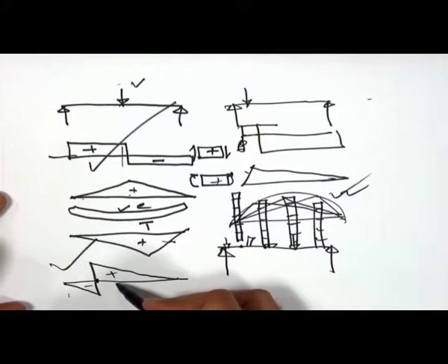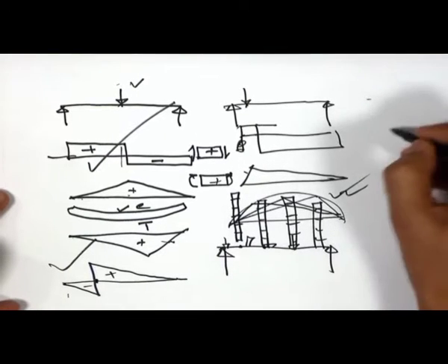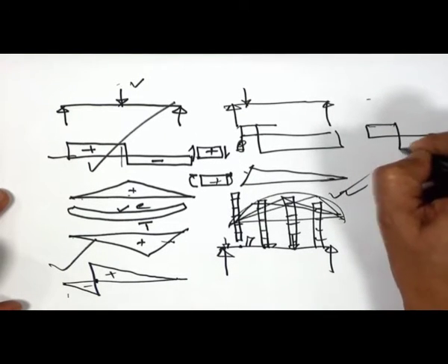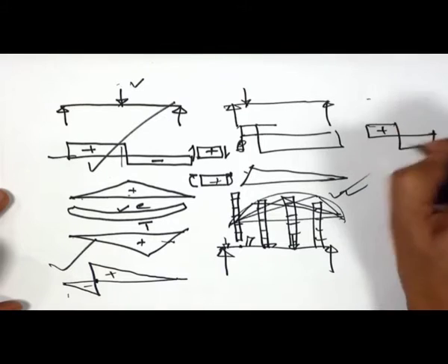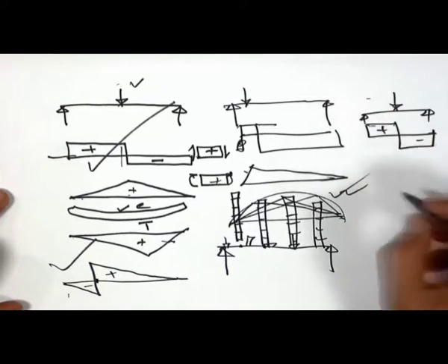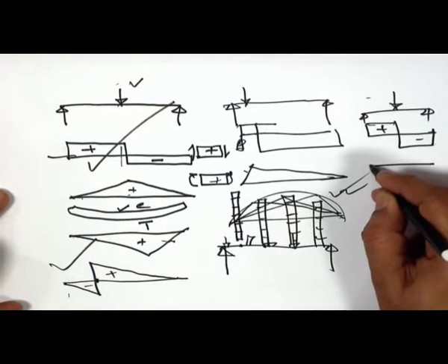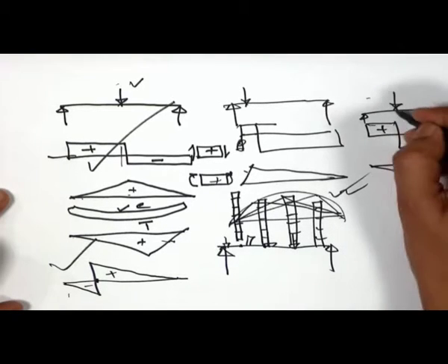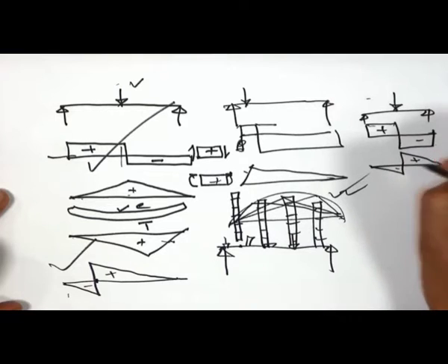I should have drawn it in the middle to comply. So, once again I am drawing it here. For you, this is the shear force diagram, with positive and negative shear for the beam which is loaded in the middle, and then you have, suppose, the influence line diagram for the shear force here, which is like this.